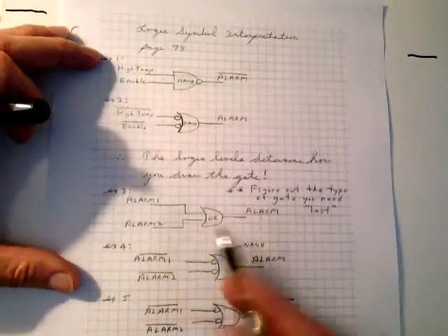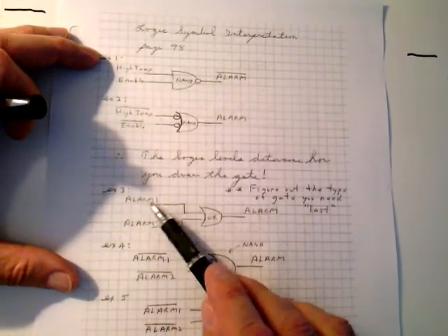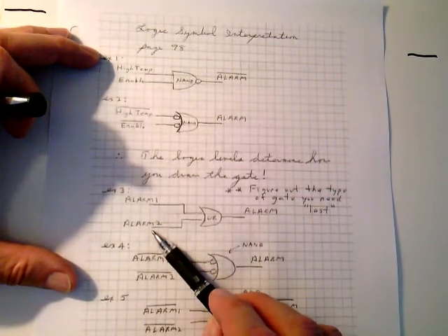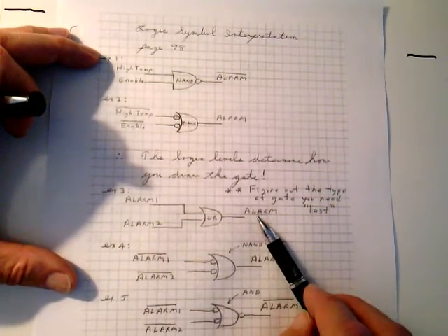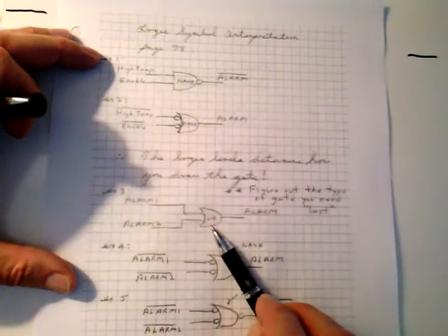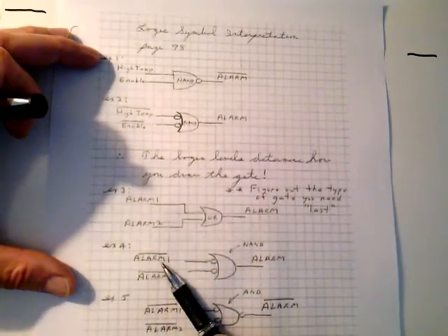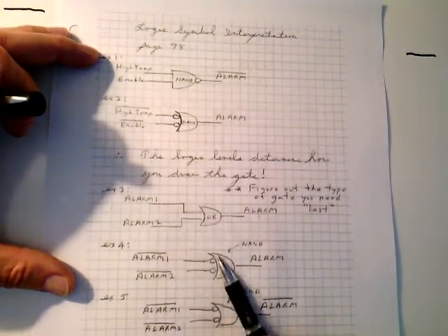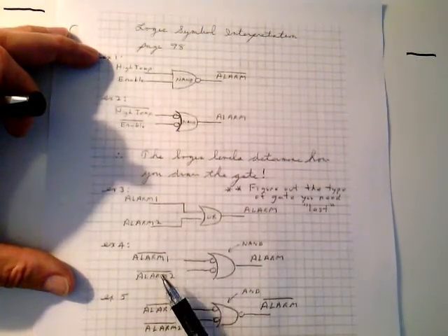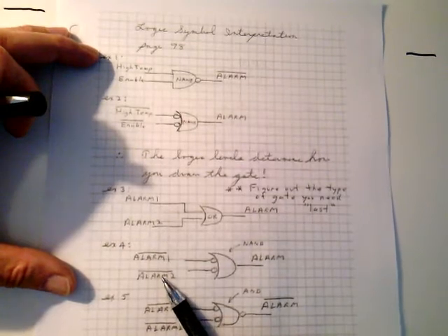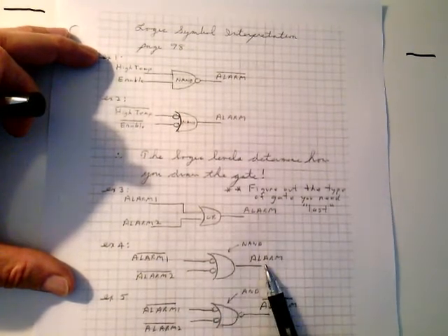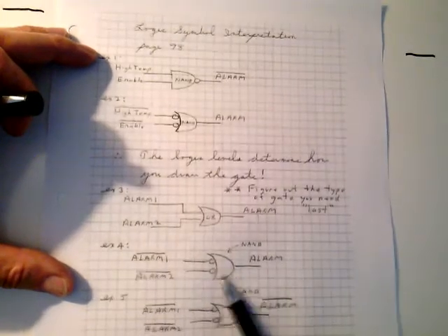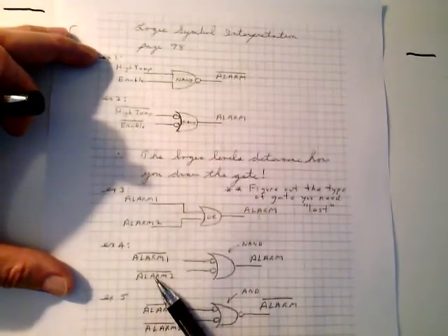Let's look down here. What if they tell you, this one's pretty easy. When alarm 1 happens, high active, or alarm 2 happens, I want the output to go to alarm. It's an OR gate. Down here, what if you have a low active alarm 1 signal? When it goes low, or the alarm 2 active, it's a low active alarm signal. When it goes low, you want the output to go high. You draw the circuit and you say, well, that's an AND gate. But you draw it like this because it tells the story.